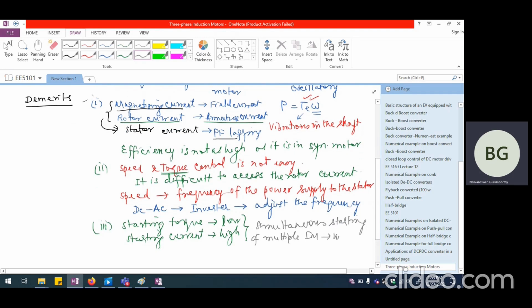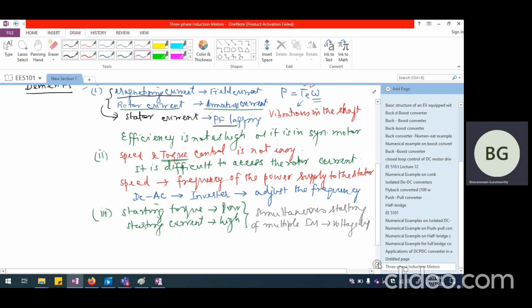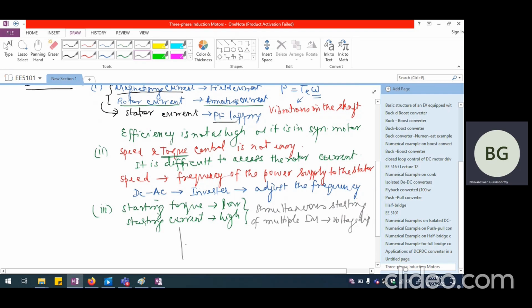You may have a sinusoidal voltage normally like this from the power system, let us say this is the kind of magnitude you are having. And when we start the induction motor, suddenly the voltage can dip tremendously. This can lead to something called voltage sag. Voltage sag is a common problem we may encounter when we start multiple induction motors.